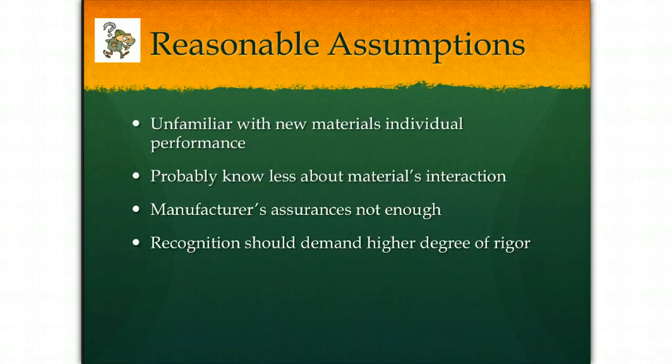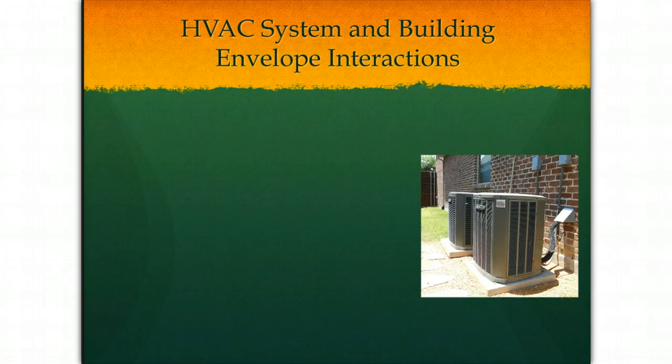As previously mentioned, the interaction between the HVAC system and the envelope creates an unusually high-risk area. The impact of this condition is that any deficiency in either system can cause dramatic building-wide moisture problems. It may be only a slight overstatement to suggest that there is no wall system that a creative architect can envision that a poor HVAC system cannot destroy.